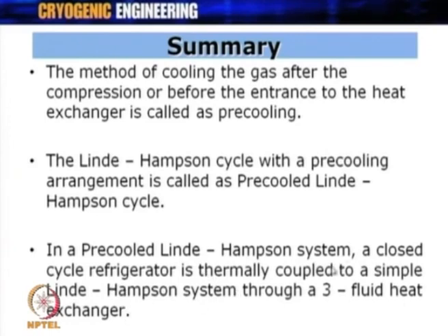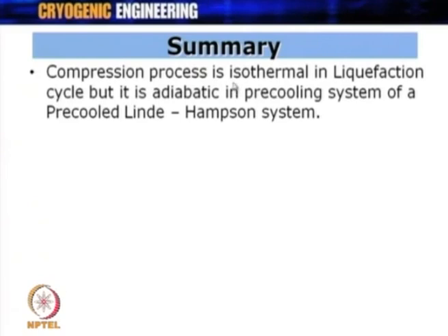So, what is important is the existence of a 3-fluid heat exchanger in the case of a pre-cooled Linde-Hampson system. The compression process is isothermal in the liquefaction cycle, but is adiabatic in the pre-cooling system of a pre-cooled Linde-Hampson cycle. These are basically the assumptions, or realistic assumptions I should say, for a pre-cooled Linde-Hampson system.